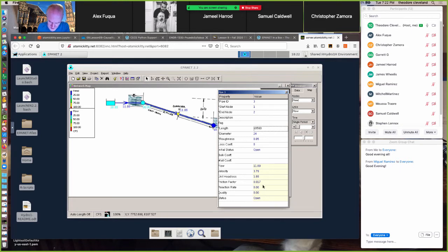I check the friction factors a lot so they don't get ridiculously small or ridiculously big. The program will report a friction factor regardless of the head loss model that you use. The friction factor is computed as if it was a Darcy-Weisbach friction factor, but it will use the head loss model you tell it to. You can use the results of this to convince yourself that your layout makes sense. Friction factors shouldn't go outside the range of values that are tabulated or on the Moody chart.